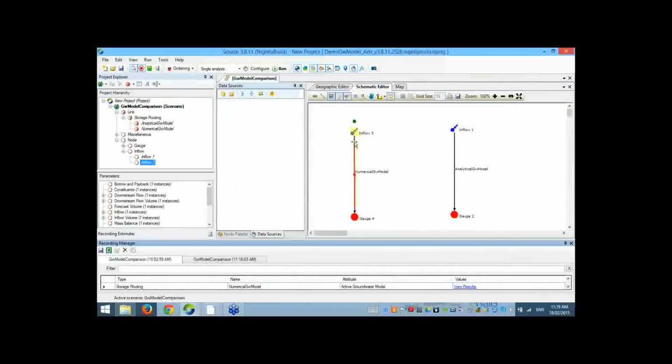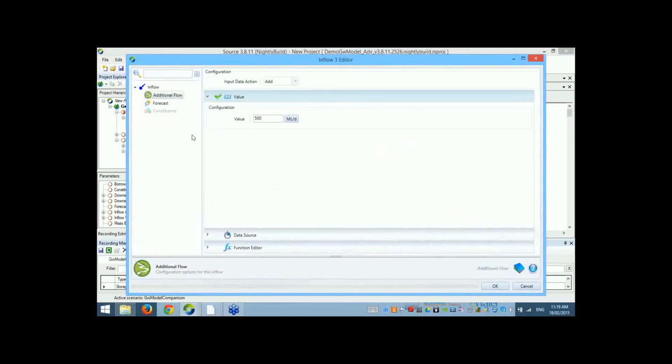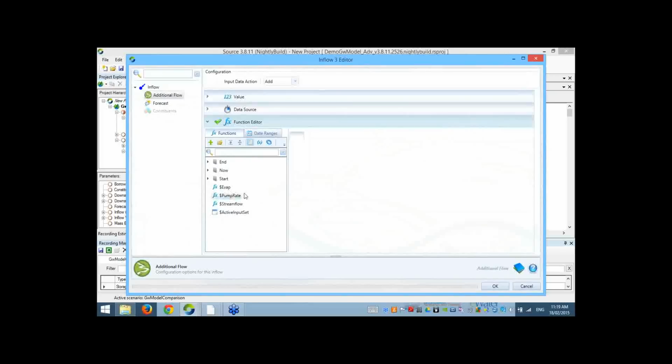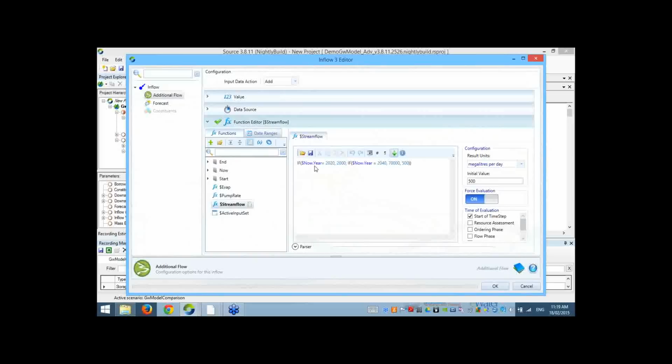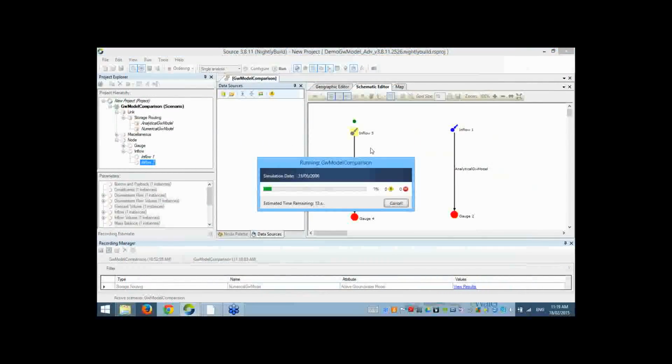The second thing that I wanted to look at, which is what I had enabled before, is the process of overbank flow. So I'll open up my streamflow and change our input streamflow from a constant value to a function which just sends a couple of flood pulses down the river. Now this isn't a realistic model, so it's actually 2-year-long floods. We'll have a look at the impact of that on the simulated heads in the numerical model.